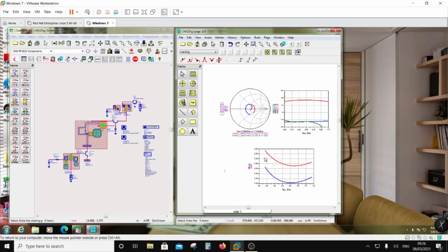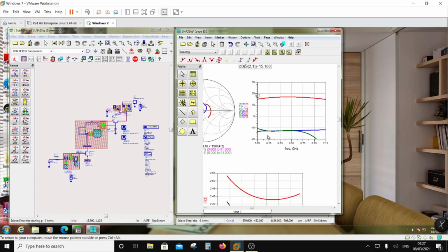It's around 0.7 dB degraded from the circuit, but that's the best I could get. And if you do a few iterations with the interstage and the input match, you might be able to drop it further. And if you do some iterations, you may be able to keep the gain above 18. Right now the gain is between 15, 17 and 15. So there is a 2 dB gain variation across the band. The return loss is better than 10 for both input and output.